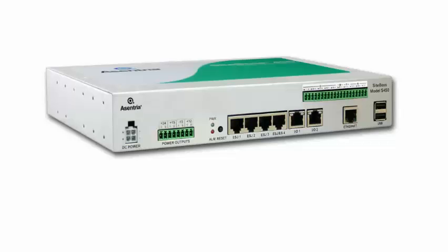The 450 has been optimized for use in typically smaller BTS sites, where a specific and defined set of sensor functions are needed. The 450 supports 2 serial ports, 1 Ethernet port, 2 USB ports, and 4 sensor ports which can support connection of external Asentria sensor and expansion peripherals. The 450 has an optional power supply for 24 or 48 volt power input. As part of that optional supply, there is a volted output bus for powering low current sensors like smoke detectors, current sensors, fuel sensors, and other powered sensor products.